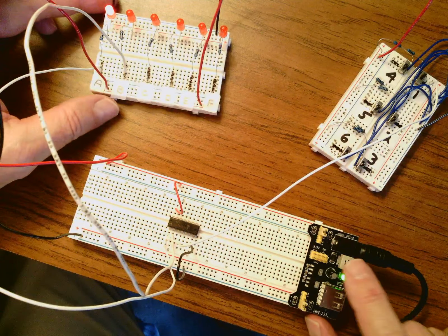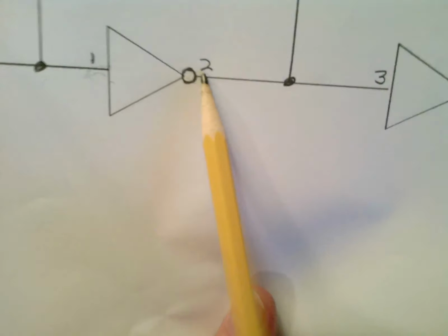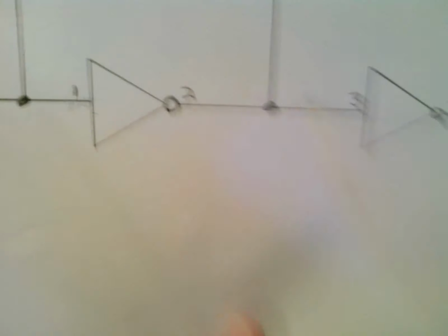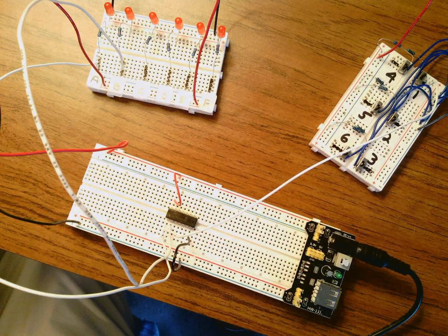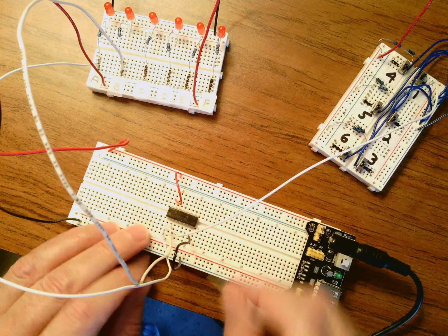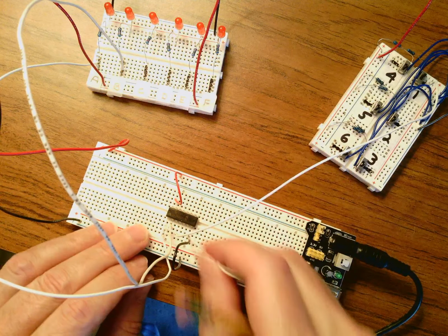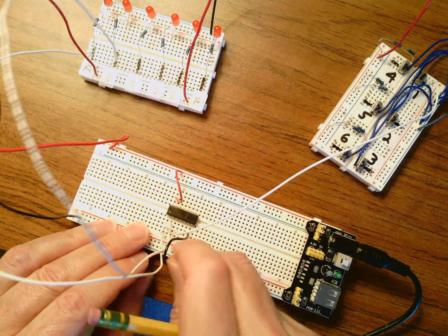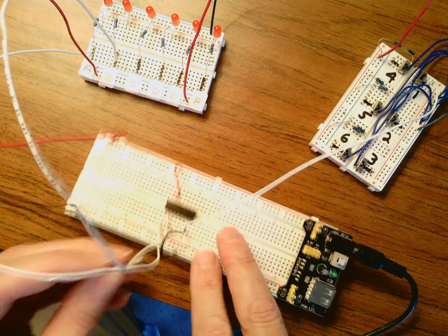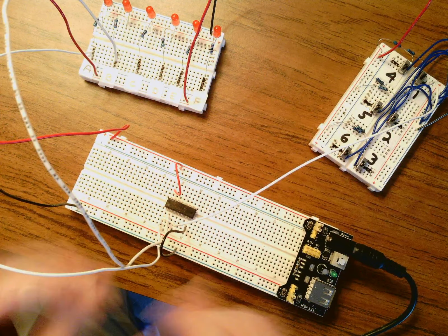And let me go ahead and build real quick. Let me go from pin 2 to pin 3 to get this second inverter in. So I'm going to get a white wire, and I'm going to go from pin 2 to pin 3. I don't need a long one. It could be any color except red and black. Be careful. You don't want to short anything out and damage your power supply. Notice I turned the power supply off.